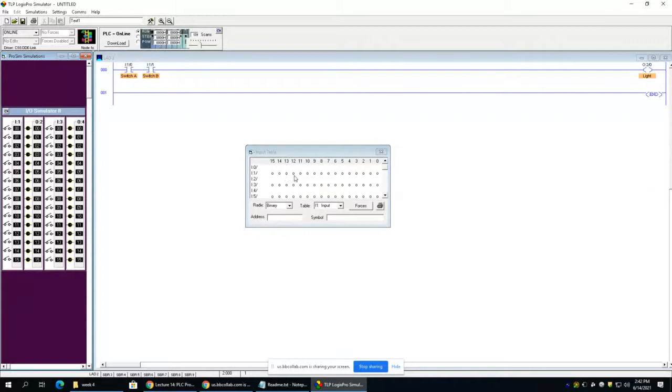So I don't have anything here because I don't have a module that's called input module 0 or input module 2. I do have an input module 1 and the input module 3, and I'm using input module 1 right now, and I'm mapped to this bit position over here. I got a switch. I'm using 0, 0, and I'm using 0, 1 on the input.